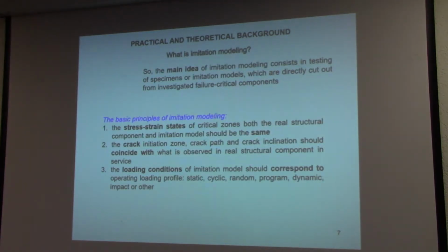So the main idea of imitation modeling consists in testing of specimens or imitation models which are cut out from investigated failure-critical components. The basic principles of imitation modeling are the following. First of all, the stress-strain state of the critical zones for both the real structural elements and imitation models should be the same. The crack initiation zone, crack path, and crack inclination should coincide with those observed in structural elements. And the loading conditions of the imitation model should reproduce a periodic loading profile.